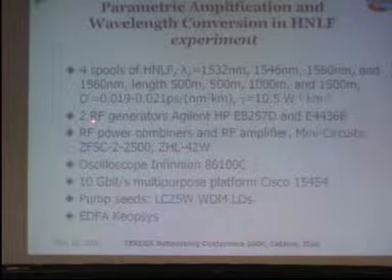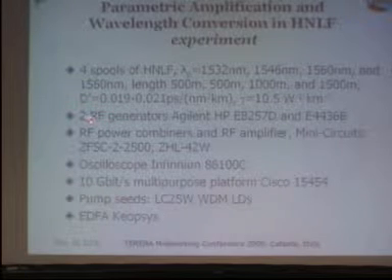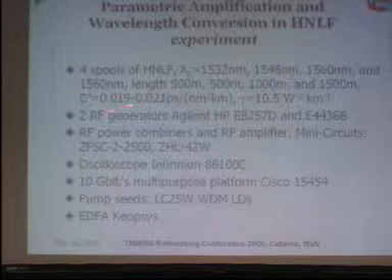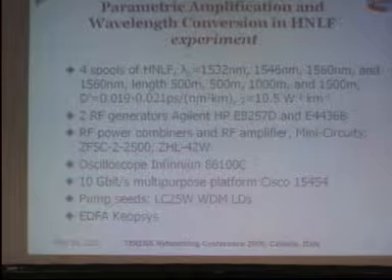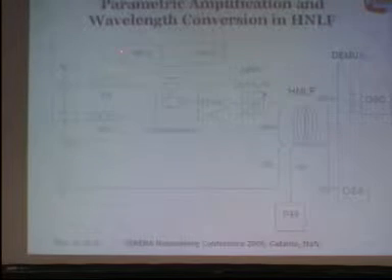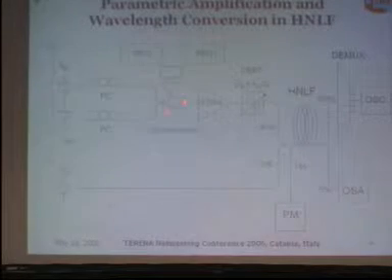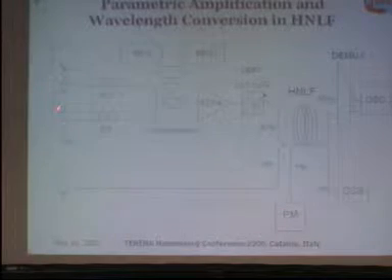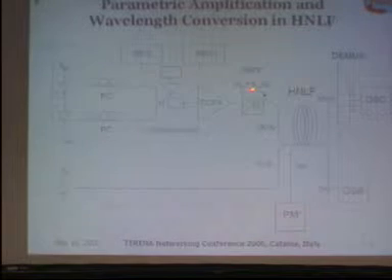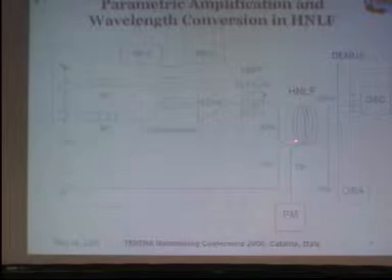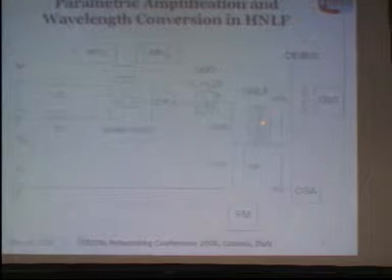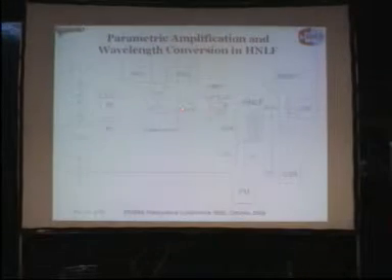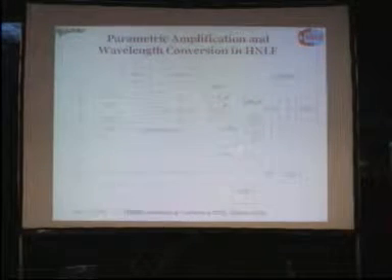To remove the backscattering generated in the fiber, we modulate the pump seeds. I come back again. We use 2 RF generators which modulate the phase modulator in order to smear the wavelengths of the seeds, or the phase of the seeds, which supports the suppression of stimulated Brillouin scattering. Otherwise, we will not be able to use all the power generated by the EDFA to be launched into the fiber.